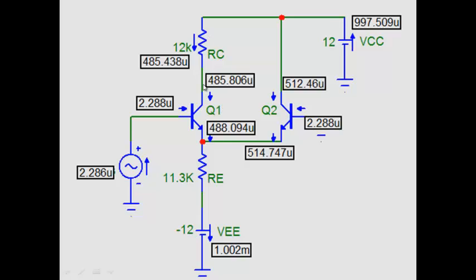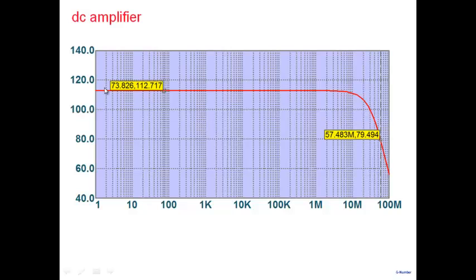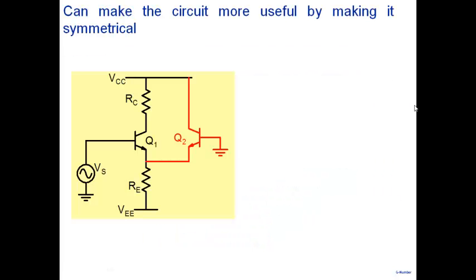And in fact, the other thing is, note there are no capacitors in the circuit, so I can even amplify a DC voltage. If I have a very small DC voltage coming from, let's say, a temperature sensor or pressure sensor or whatever it is, you can apply a DC voltage also and amplify it. So it can amplify a DC, AC or whatever it is, and therefore the frequency response, if you see here, there's no lower cutoff frequency at all because we don't have any coupling capacitors. So it amplifies right from DC onwards to some higher frequency determined by internal transistor capacitors. Okay. All right. Now, this is the solution that we arrived at.